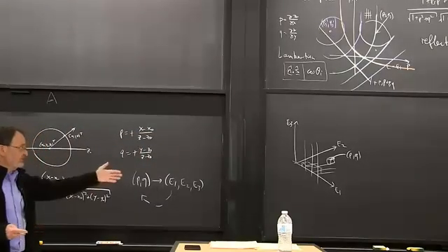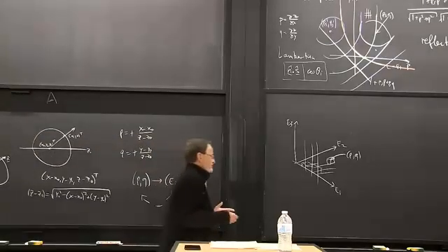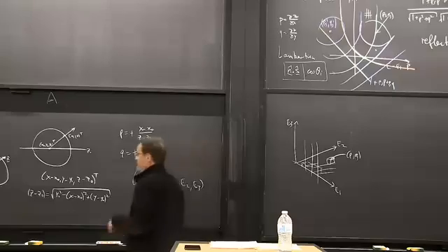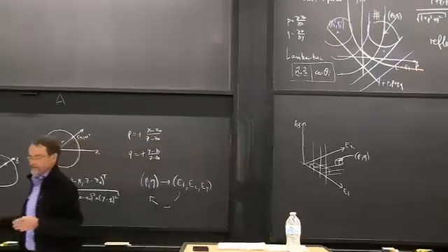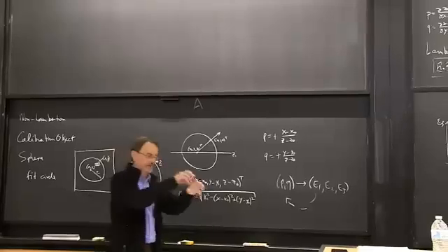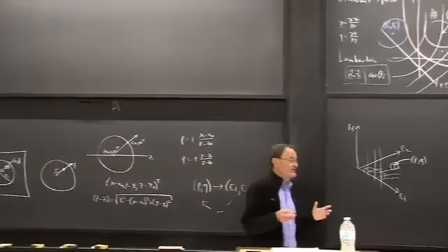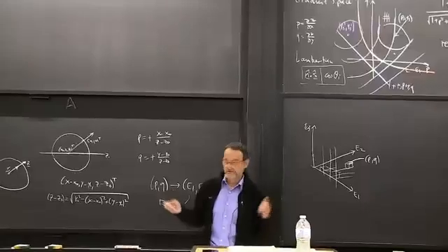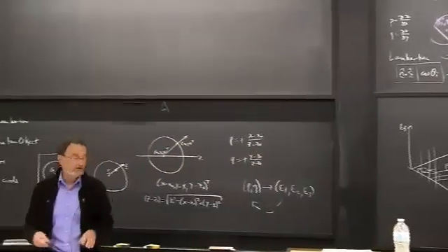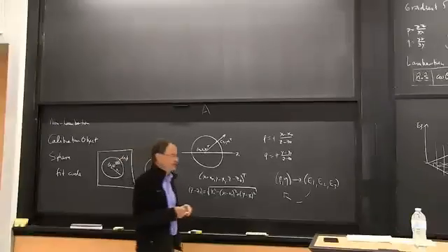But in any case, that means we need to quantize, and we might need to quantize fairly coarsely, like 1 in 100. And that means that some of these points happen to produce the same rounded off values, and so they'll be riding on top of each other. So that's one issue. How do we deal with that? Well, one way is to average them, because presumably they're slightly different P and Qs, and by combining them in some weighted fashion, we can get higher accuracy.